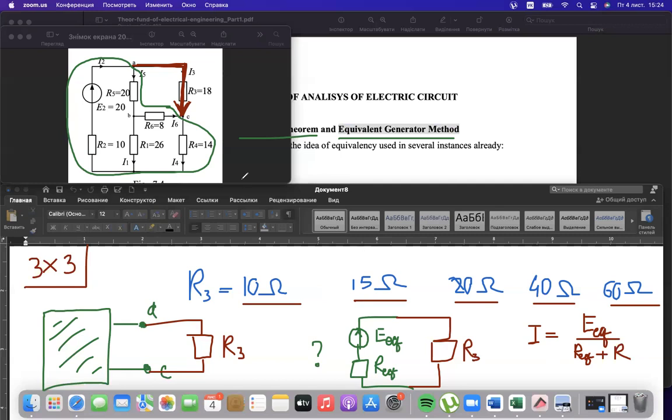It is quite a bit easier. And just imagine, here there are only 3 meshes. But if you have a big system, for example, with 1,000 meshes, you have to find the solution of a matrix of dimension 1,000 by 1,000. And for example, you want to search for 100 different values of resistances. You have to solve this matrix many times. Instead of it, you could use only one formula, also many times. It will be much easier for the computer, for quicker calculation, and it is the main idea why we are interested in this method.